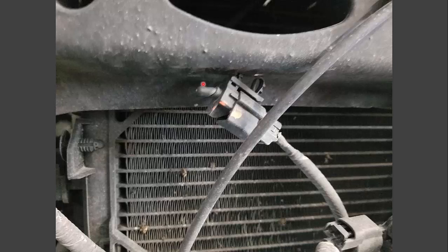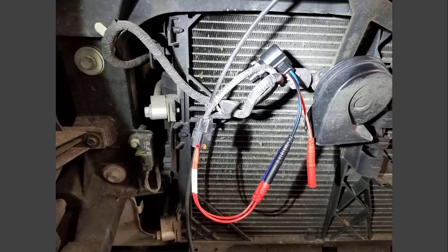So I want to be absolutely sure this is the only issue with this vehicle, because you will see that I found a broken wire already. With the airbags, we're going to see some more wiring issues on this car in a couple minutes here. So I want to make sure that there's nothing else going on, especially if it's in an accident. That harness could be damaged. So what I did is I got these breakout leads recently from AES Waves, so I was able to put my leads here into the connector, and then that kit comes with a variable resistor.